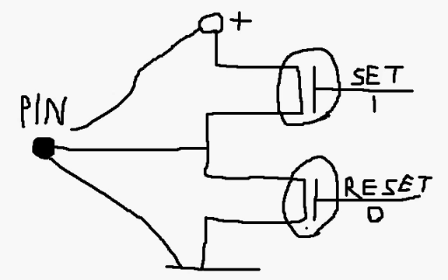On the data bus, since the pins are bidirectional, there's also another line that kind of snakes down like this and goes to another section, which I'm not going to draw here for now. But that's basically how the outputs work. I believe that's how the address bus pins look, if you look at how the address bus works inside the 6502.